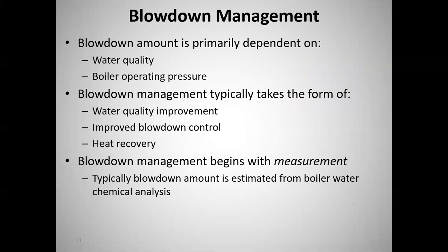Okay, so blowdown amount is primarily dependent on water quality, how good your makeup water is, and your boiler operating pressure. The higher the pressure, the more likely it is for scale to form. And so your water has to be purer and purer and purer.